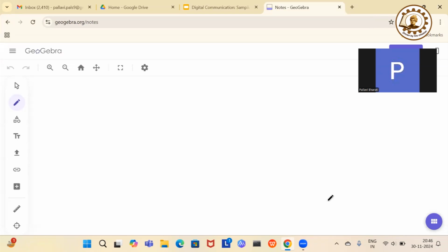Let's see for once. So what we are going to do is, we have this signal x(t), which was our main signal. Then we had the signal delta Ts(t), so the delta Ts(t) was our train of impulses. We are going to multiply this with the h(t).